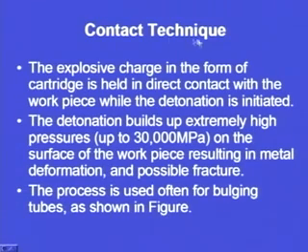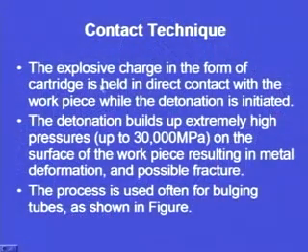In case of the contact technique, the explosive charge is in the form of a cartridge. In case of the standoff technique, the explosive charge may be of any kind; it can be some chemical, or a gaseous mixture, or some kind of a propellant. The explosive charge in the form of a cartridge is held in direct contact. An important point to note here is the direct contact with the workpiece while the detonation is initiated.